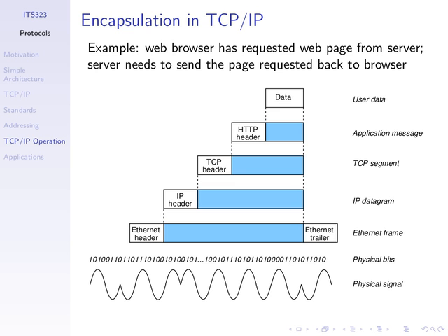The total amount of data that we send is, in bits, 80,864 bits. We can either do the calculation in bytes or bits, as long as everything's in the same units, it's okay. Our data rate is given in megabits per second. That's 1 million bits per second, the rate at which we can send.